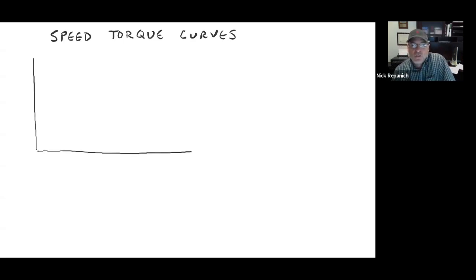We'll do this later in the semester, where we start actually picking motors based on some of those parameters I just gave you, inductance and constant current versus peak current. But for now, when you just need a motor that produces 12 foot-pounds, you're going to try and find a manufacturer that's already done all the testing and tells you what amplifier to use to drive the current. So you're going to try and find something.